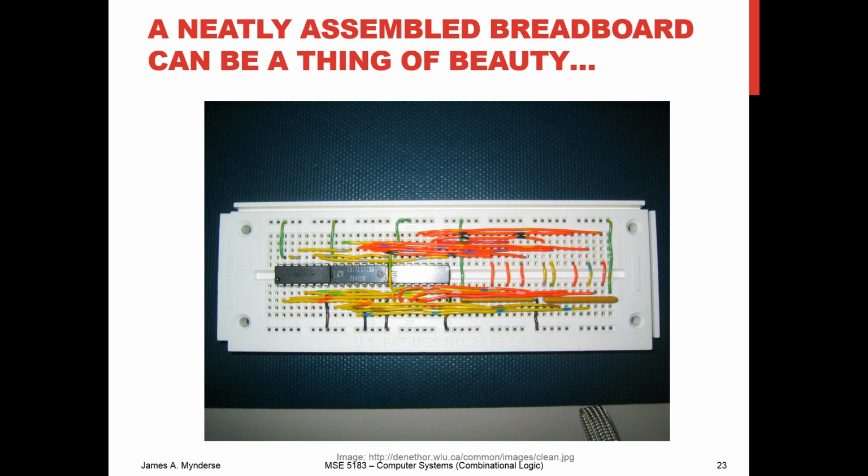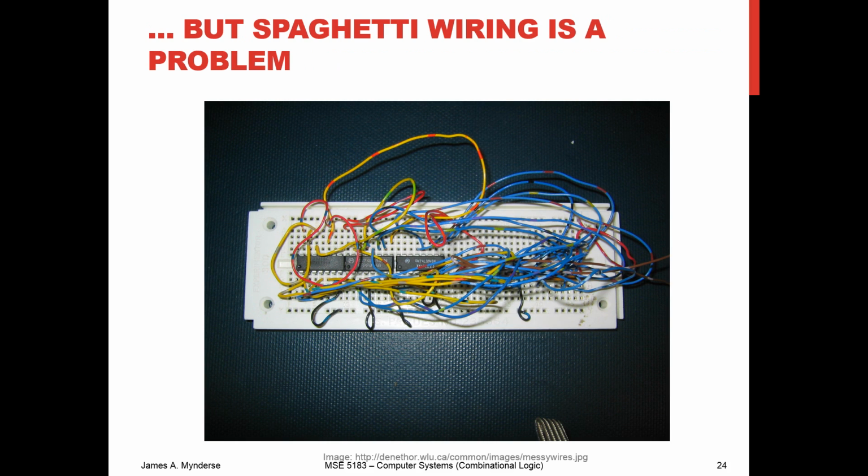So if you were laying these out on a breadboard, you might make something like this using just 7400 ICs, and this would work very well. Although that's a lot of wires, it's a lot of debugging, which is kind of difficult. But if you're like most students I've met, you'd actually make this one, and that's almost impossible to debug.